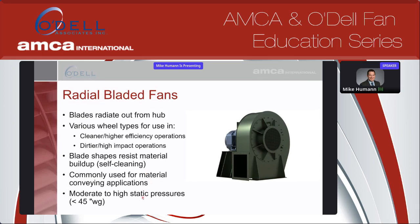Moderate to high static pressures here. Volumes can be relatively low on radial fans to kind of a medium volume. Volume wise, because of the small outlet, you can't go really high in volumes because you're going to have a really high outlet velocity. So you'll have losses, and you could have issues with sending a large velocity of 8,000 or 9,000 feet a minute down the ductwork, which causes noise and can cause other concerns as well.